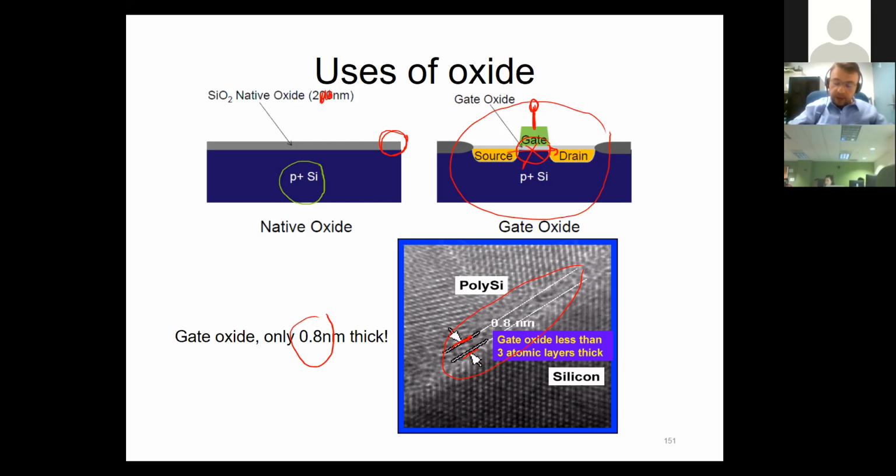So we have the gate as the polycrystalline silicon in this case. So I can see some arrangements of the atoms, but it's not going to be like the crystalline silicon, where I will end up with what we call the grain boundaries. As for the silicon, I have a fully nice arrangement here underneath. And here I again end up with the amorphous material that I was emphasizing.